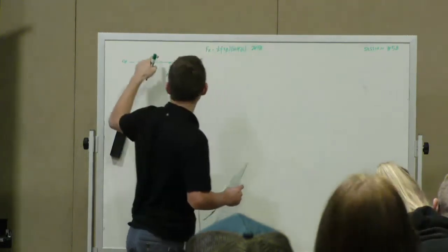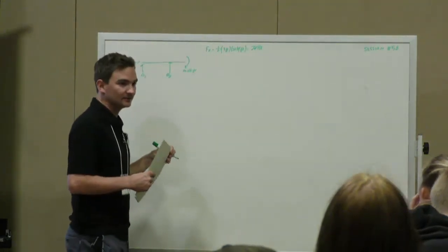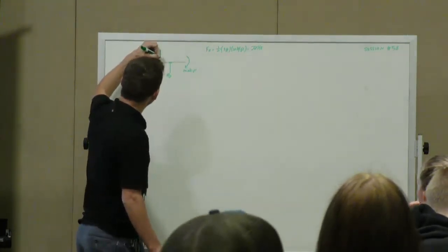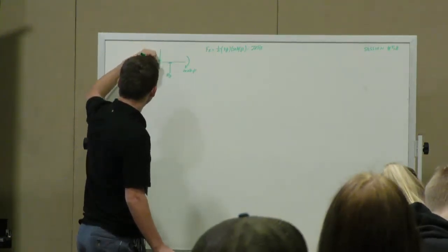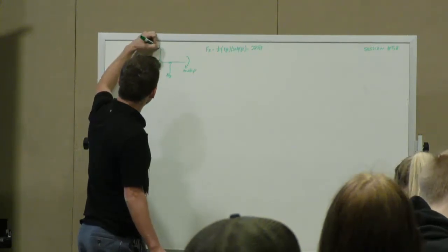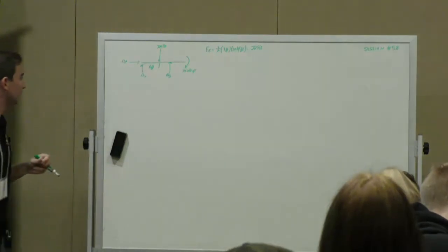So now what's the distance going to be? How do we determine that distance? Yep, very good. So it's 2/3 from the light end or 1/3 from the heavy end. So that's going to be 2/3 of 9, which is 6 feet. And the magnitude is 225 pounds. All right, so now what do we do once we have the free body diagram?